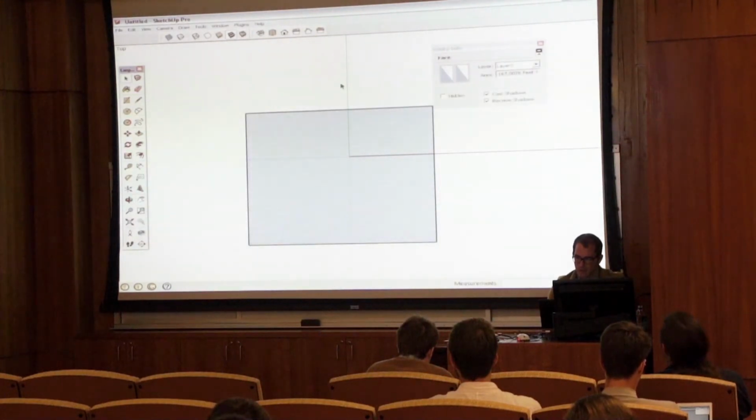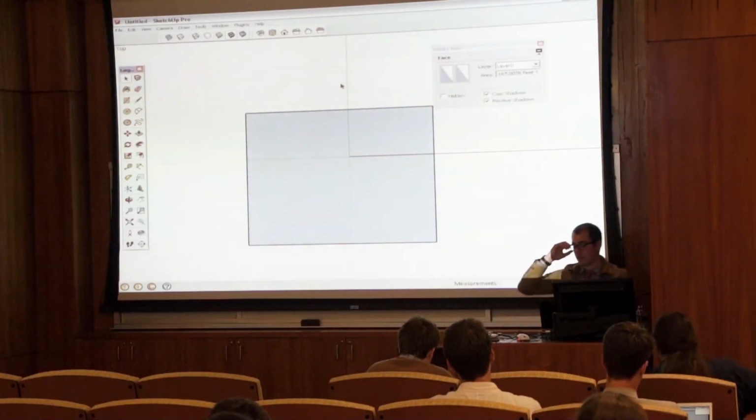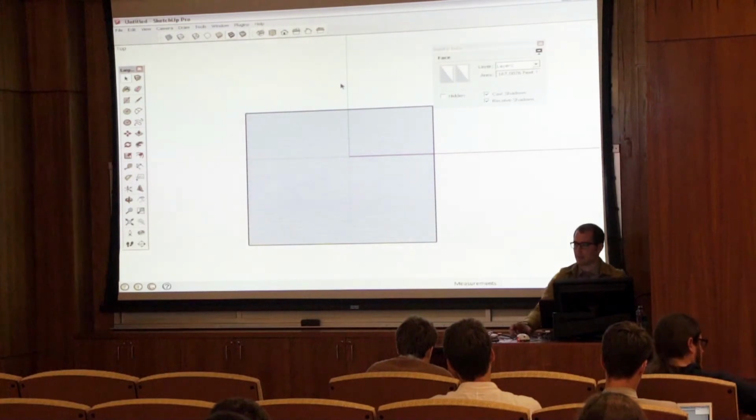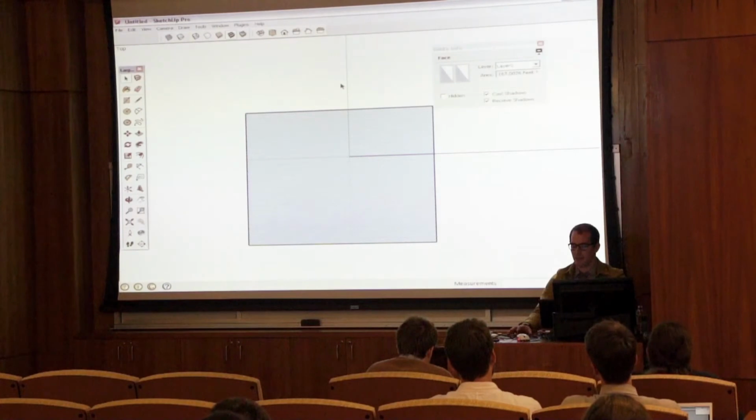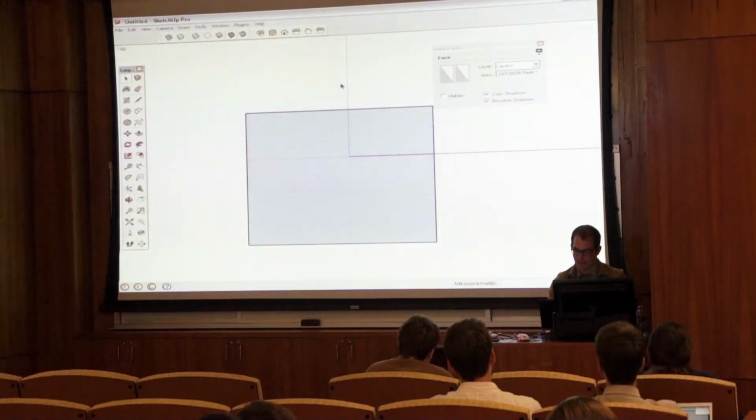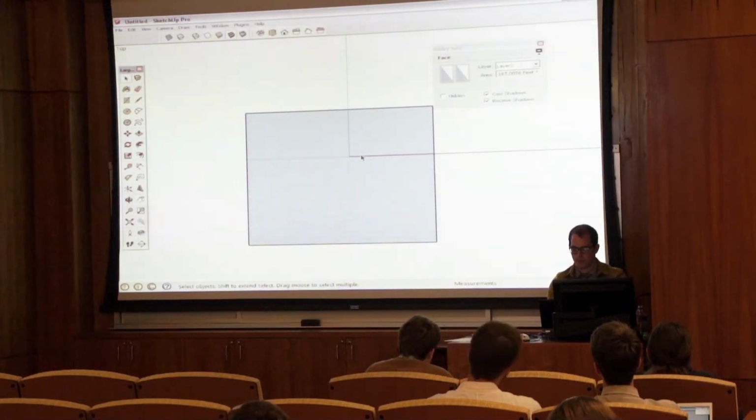A is arc. A lot of your tools are basically off of there, as well as when you're in 3D eventually, you use Shift a lot to pan. So if you orbit in SketchUp and then hold down Shift, it actually allows you to pan. So that way, that's always useful. But if I don't have a mouse, I'm usually using my thumb as my left click, and my index or middle finger of my right hand to navigate.